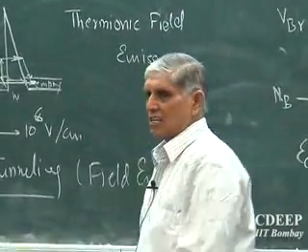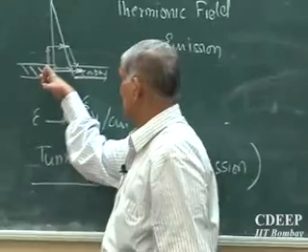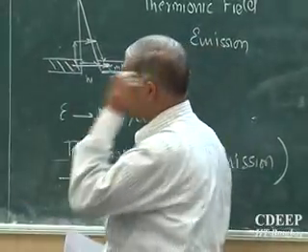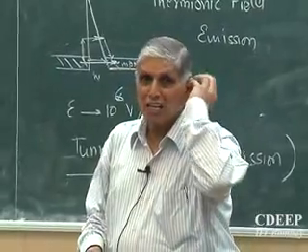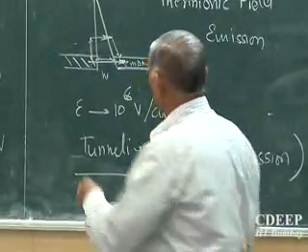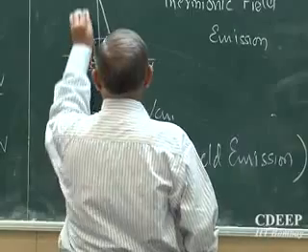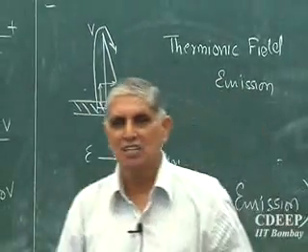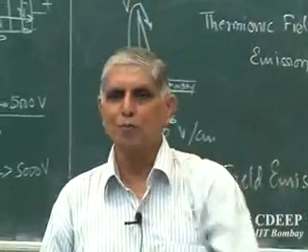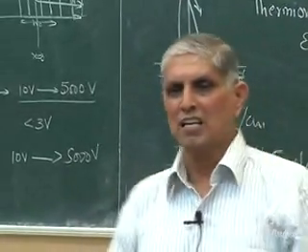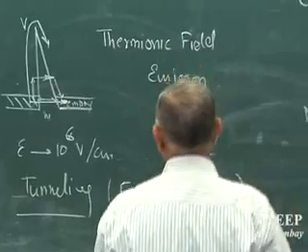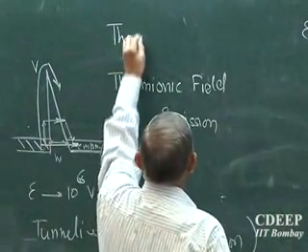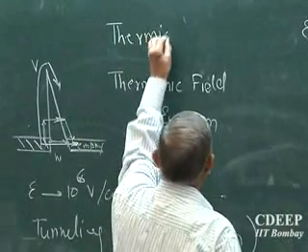But let us say these states are not available like this, the barrier is also high, no tunneling or thermionic field emission can happen, but you still keep putting in energy which crosses this barrier energy, then also it can go from P to the N side. That is, when the electrons reach the full barrier height and then drop, it is called thermionic emission.